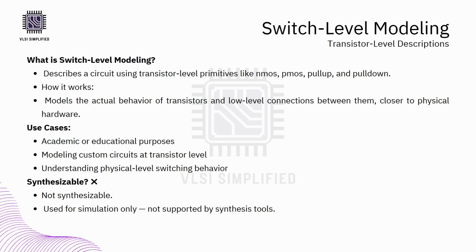We'll usually use switch level description in educational examples or when someone is modeling custom cells like an SRAM bit cell or a latch. However, it's important to note that switch level code is not synthesizable. It cannot be converted into gates or mapped onto an FPGA or ASIC using synthesis tools. It's only useful for functional simulation and understanding low level operations. In the next slide, let's look at how we can implement an AND gate using switch level modeling.